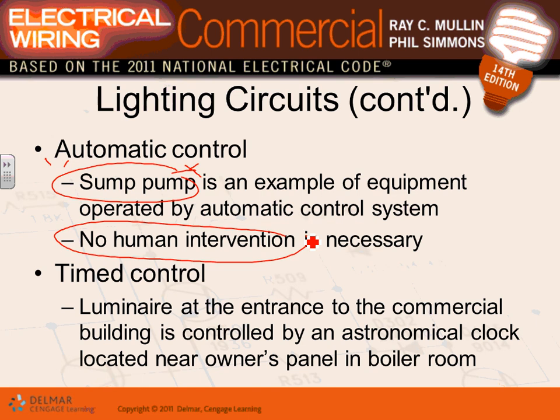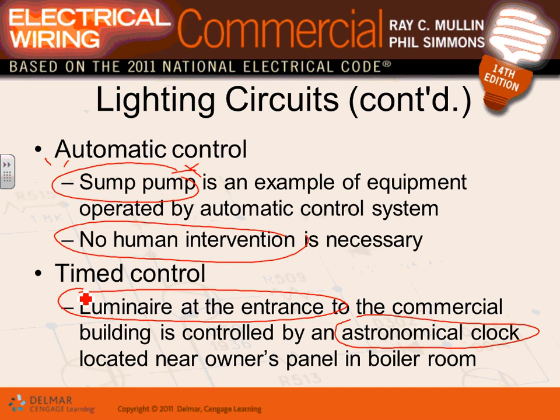Timed control. They did the timed control with an astronomical clock located near the owner panel, and they did it, guys, for the luminaires at the entrance of the building. There are some big luminaires right at the entrance of the building, and they assigned an astronomical clock to them. So turn on at a certain time: on at 6 p.m., off by 6 a.m.